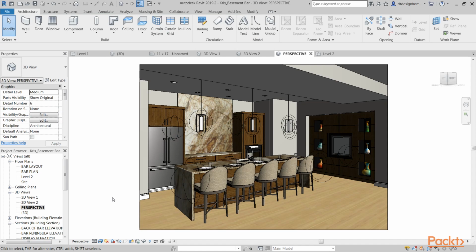So do a low quality, just really quick render to see what the scene is actually going to look like, and make sure you don't have any really bright spots or kind of issues where you have a really dark shadow or a weird shadow being cast, because if I don't have my fill light set just right, this light that I have over here might cast a really harsh shadow of this pendant light all across the ceiling over here. And that's not something that's very realistic and not something that I really want to see. So getting your fill lights correct can be really important.